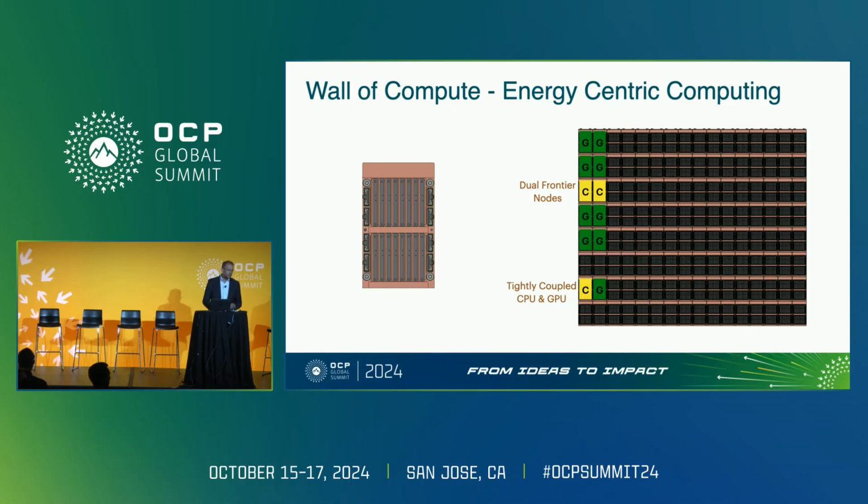Another example is we could emulate the Grace Hopper configuration. If you know the Grace Hopper from NVIDIA, they have something like 7 times the PCI bandwidth, or 1 PCI Gen 5 channel between the Grace and the Hopper chip. You could cable this together to give you that same bandwidth between 2 modules, a CPU and a GPU module, so you could emulate Grace Hopper.